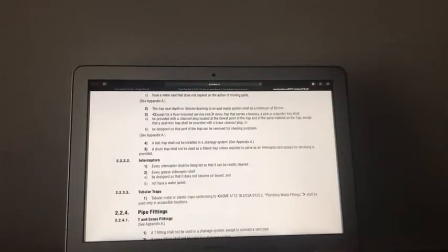Now let's talk about what's normal, what's not normal, what you can buy at the wholesaler, what you can't buy for a second. So floor-mounted service sink, I'm 99% sure I remember seeing a brass plug in my trap below the floor in the parkade for a hospital. Let's move on to a lavatory and a sink. Later on, we're going to build some lessons about those around cleanouts and what they need, what they don't need.